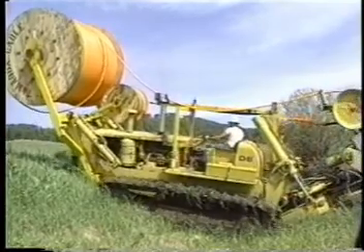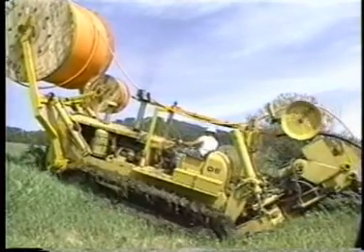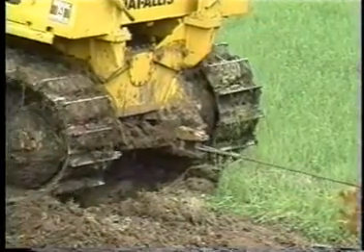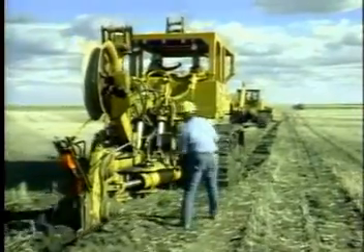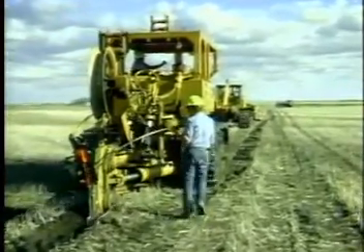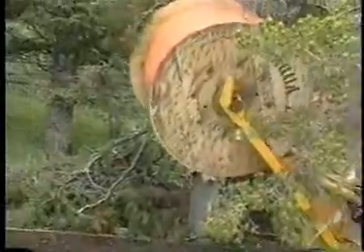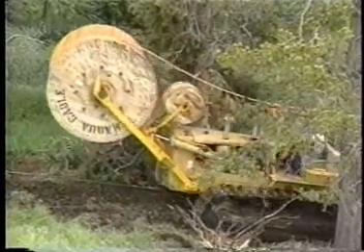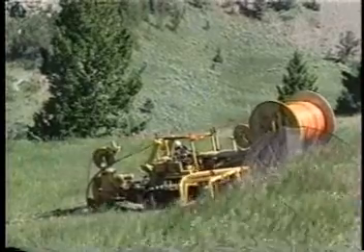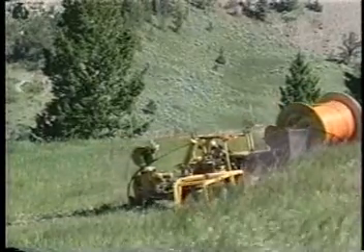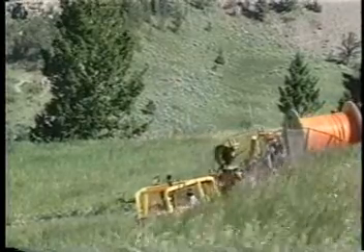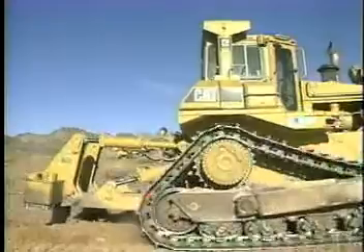Variations in cable tension are caused by startup, uneven terrain, speed changes, and unexpected obstacles, and can easily rise to unacceptable levels. Armored fiber optic cable is most often placed directly underground by plowing, but the possibility of cable damage can be reduced by either plowing in duct first and installing cable later, or installing cable in duct in a single operation. In either case, tension on the cable is significantly reduced when duct is used. The added protection offered by the duct allows the use of armored or unarmored cables in these spans.